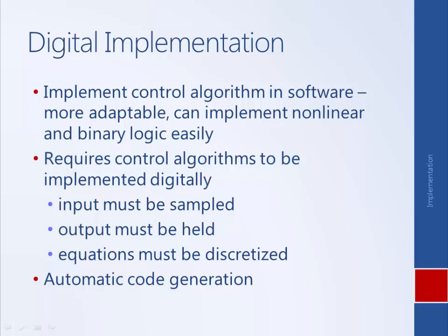And so the development engineer has this high-level model of the control system, and he can generate the code that's going to run on board the vehicle just by hitting a couple of keystrokes, and it will automatically translate that Simulink model into control code that runs in real time on the vehicle.